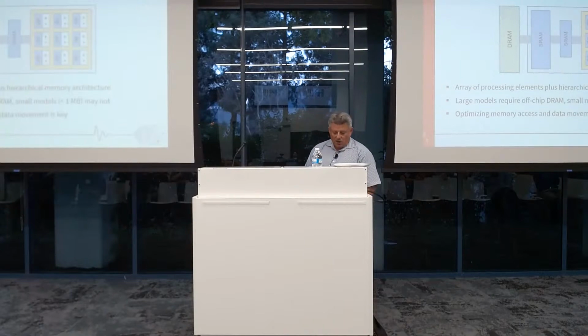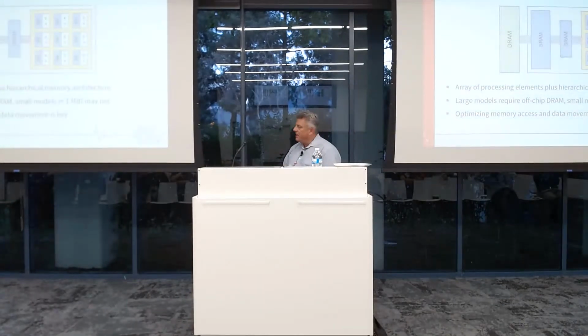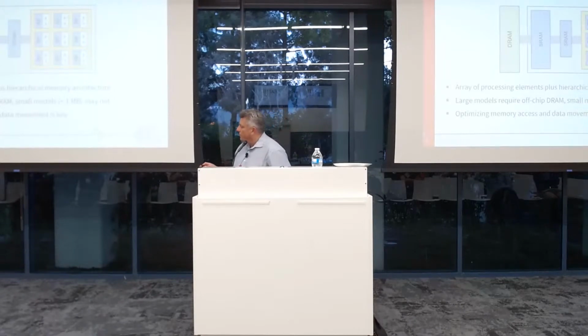So if you have a model that's, say, bigger than a megabyte, I would say people will often go to DRAM, because otherwise the chip will be too big. Squeezing more than a megabyte of DRAM on a chip is hard. You can do it, but then the chip gets pretty big again. And so this is sort of the breakpoint for DRAM.